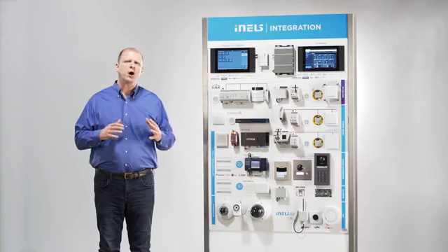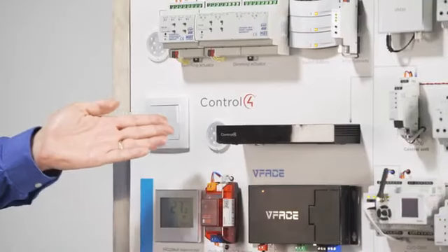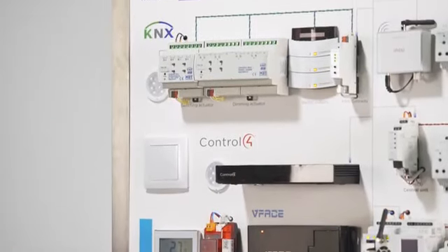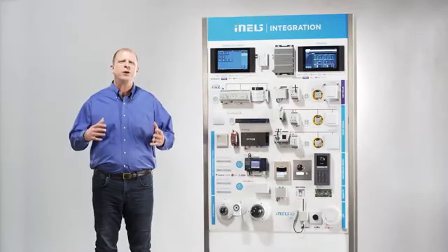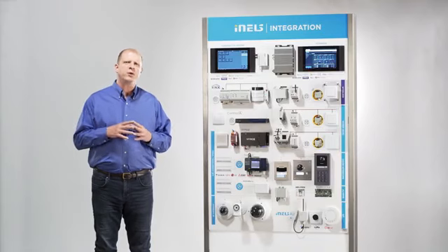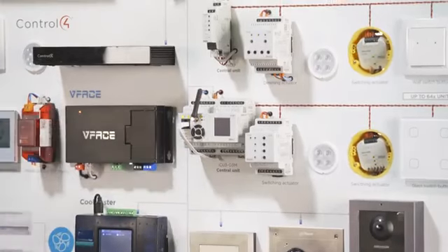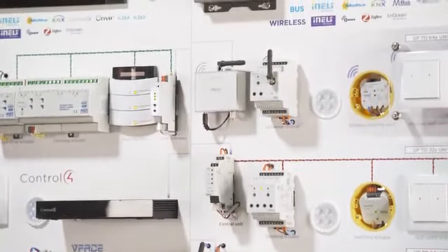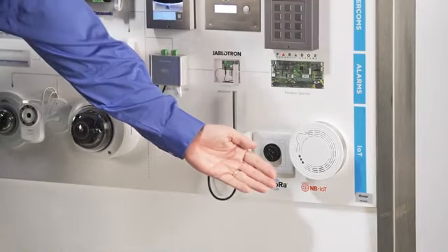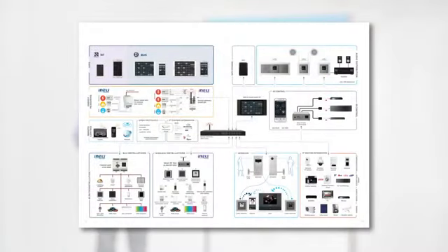This is demonstrated on a selected example, for instance, multimedia by Control4, or switch control by ABB based on KNX protocol, and so on. The key part of the installation is a computer network used by the central unit CU3, gateway ELAN RF, or by iNELS air sensors, transmitting data over TCP IP protocol.